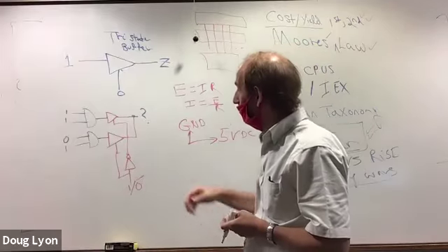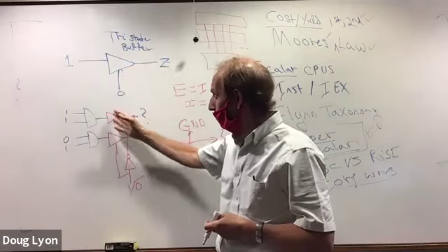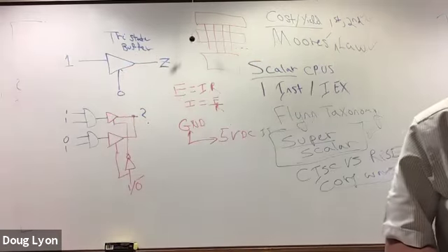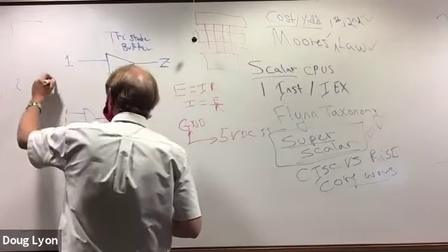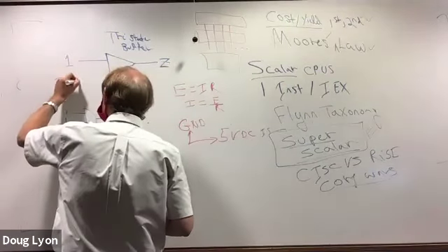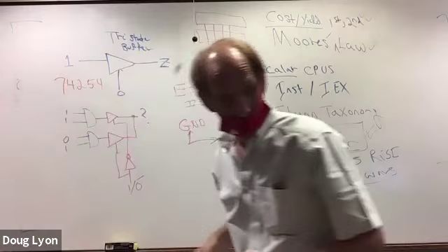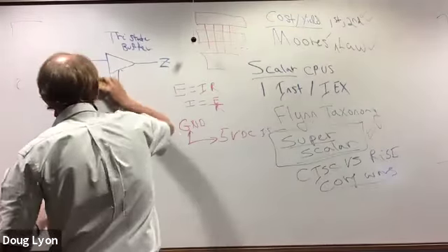And so what you need is tri-state buffers, which are going to drive the bus. Now, in the case of the chips, which you can find in our stock room, you can find a 74254. I think that's the number. Let me just check it. Nope, I got it backwards. 245.